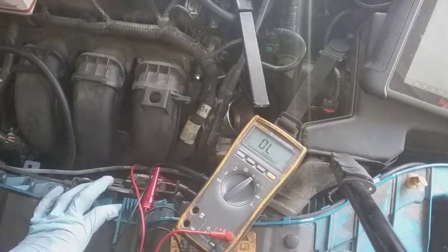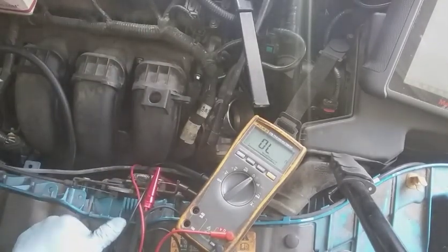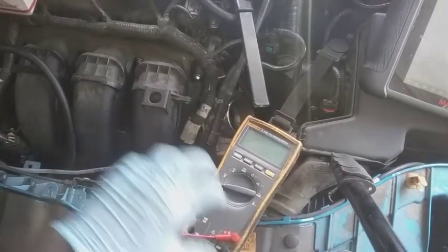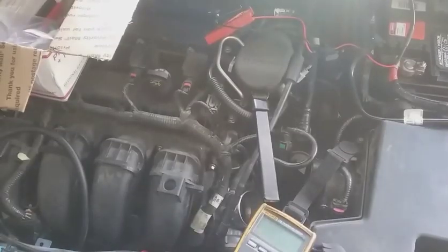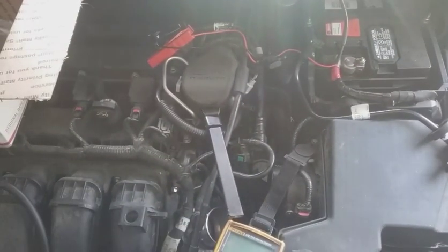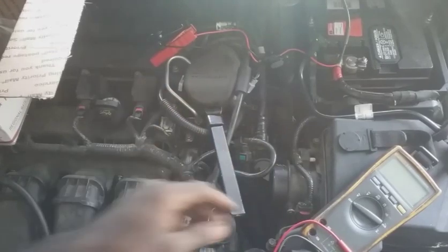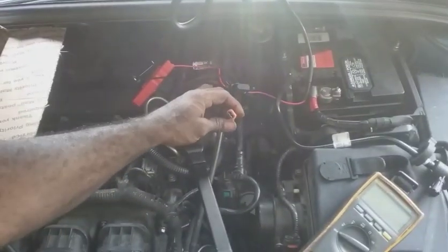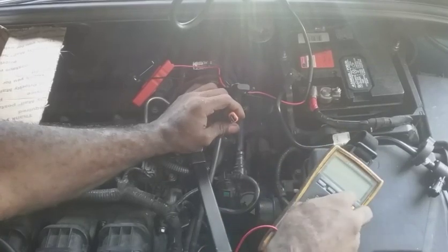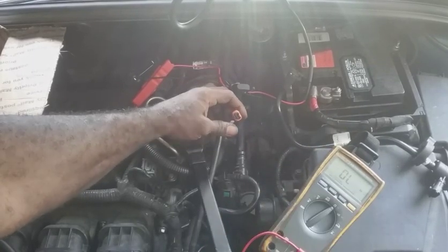and also do a resistance test on the new one also. So we're going to do that. I'm going to go to O'Reilly's now and get our new part. While it's fresh on my mind, because I want to do the basic circuit test with the key on, engine off, and I want to show the resistance value of the circuit here.